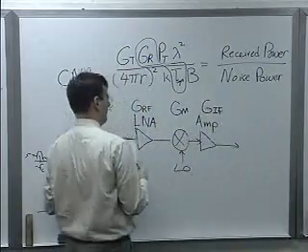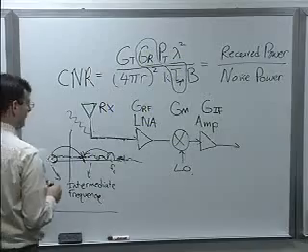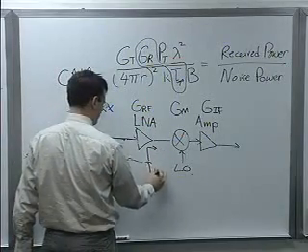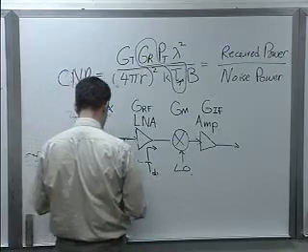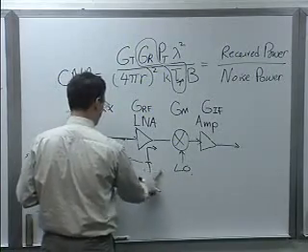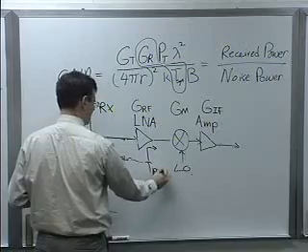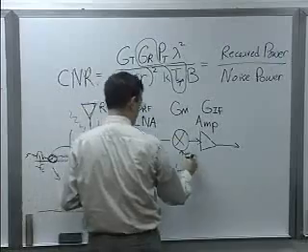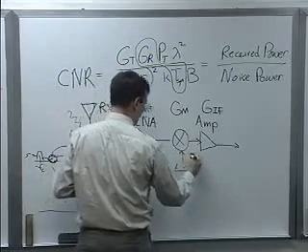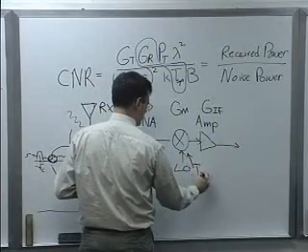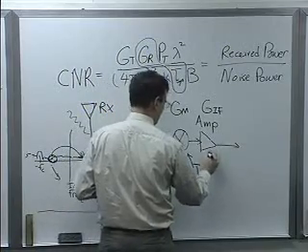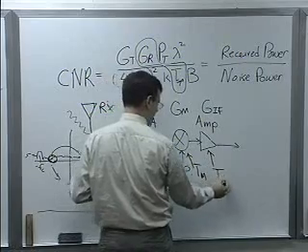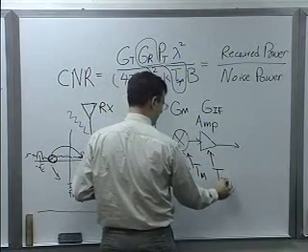Mixed it down to an intermediate frequency. And each of these devices is going to have device noise. So let's call this T RF. Let's keep our subscripts consistent. A device temperature in kelvins for the first amp that adds noise into it. Device temperature for the mixer, T sub M. And a device temperature for this amplifier here, T sub IF.